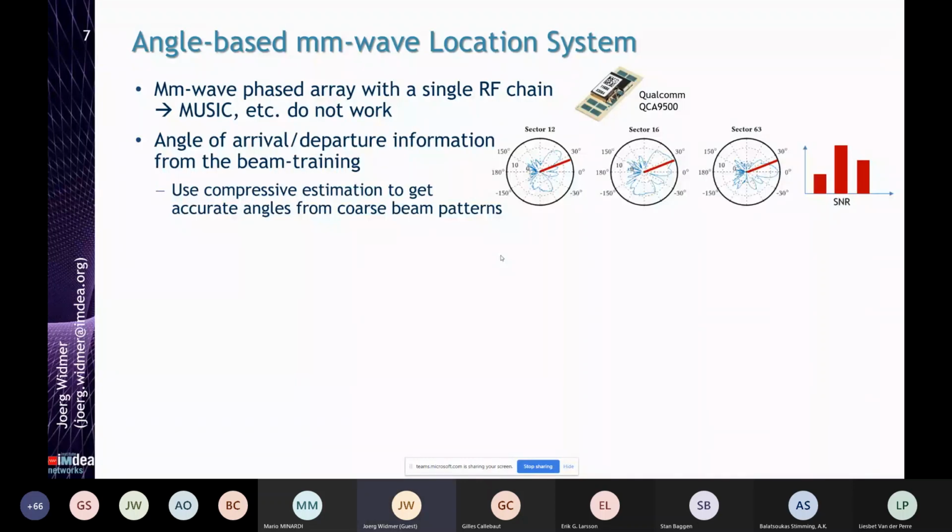Now, you can still get angle of arrival and angle of departure information in many different ways. I'll just highlight a very simple one here. So what this shows is a few different beam patterns, right? These configurations that are shown with very nice narrow sectors before, in reality, they look a bit more ugly, like we see here with this blue outline.